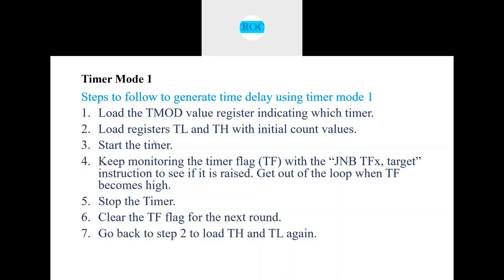Next, load registers TL and TH with initial count values. By default we have a value of 00, but you can have any initial count value there.